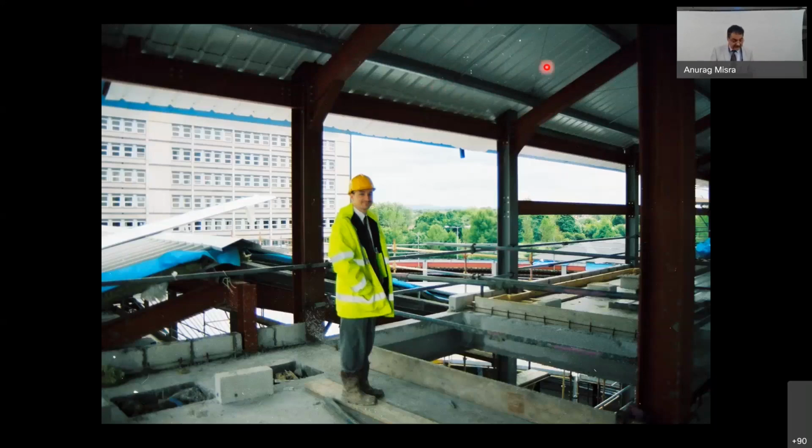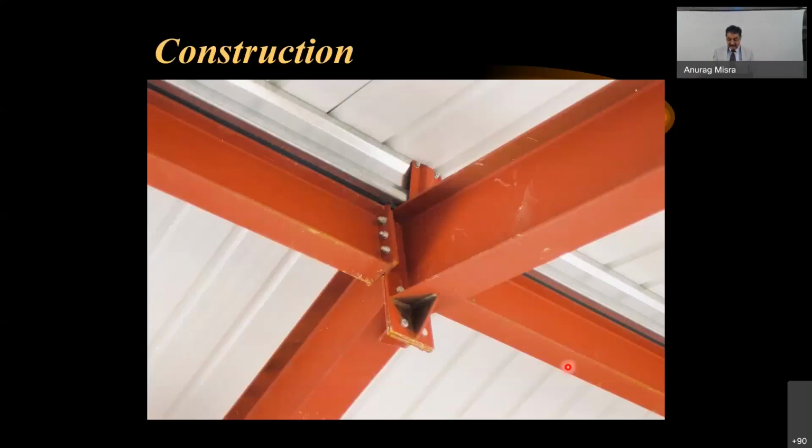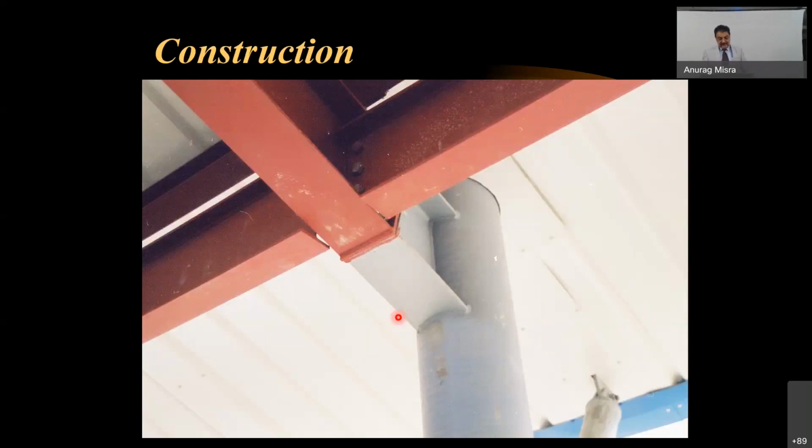So these are all panels, and these are the staircases, and this is the connection from a typical building where you need moment connection. You have to actually increase the lever arm and create some kind of connection which is able to carry the same kind of load. You cannot use different kinds of bolts. So you have to adjust your joint wherever possible in a way that you are able to manage the forces coming into the bolt. In some of these specifications, the connection to the main column is prohibited, right?